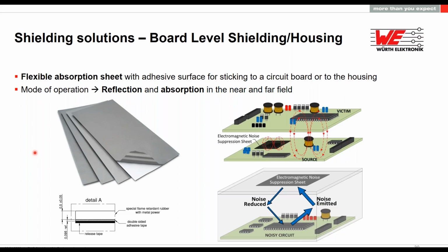Yes, sure. There is, because when we're going to higher frequency, there are small slits that cannot be prevented with the clips. If we solder the shielding cabinet, that at the end is a Faraday cage, straight directly to the PCB, then we are also shielding against very high frequency. With the shielding clips, there are small slits or slots, and with very high frequency signals this can become problematic.